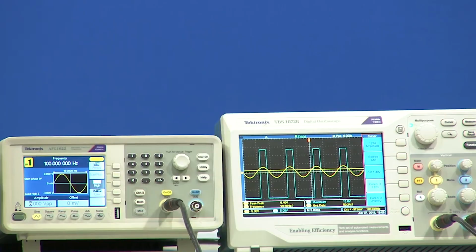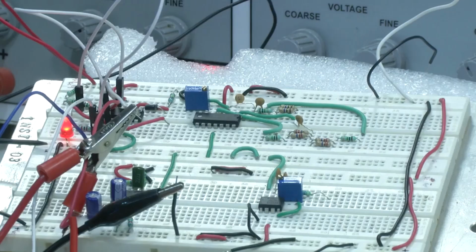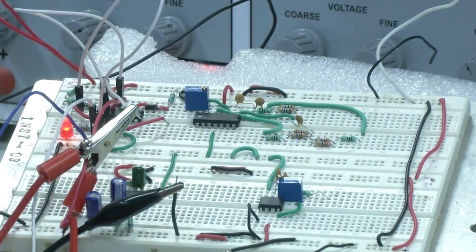But when we look into the board, we can see the LED is continuously glowing. We cannot see any flickering of the LED, like on off on off. The reason is the frequency. The frequency that we applied is 100 hertz, and it is very hard to understand with our eyes. So, I will change the frequency to human understandable values, somewhere around 30 or 20 hertz, where we can easily visualize it.